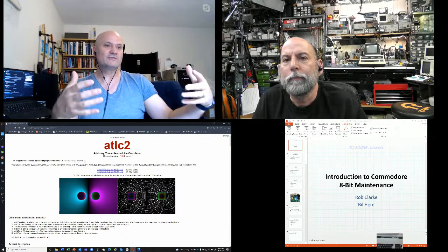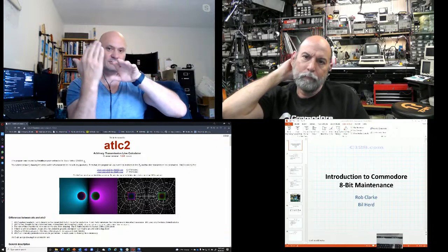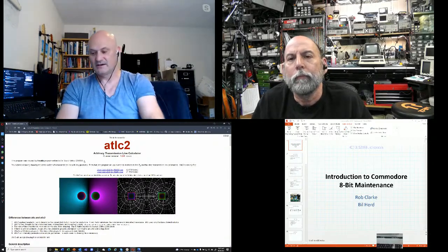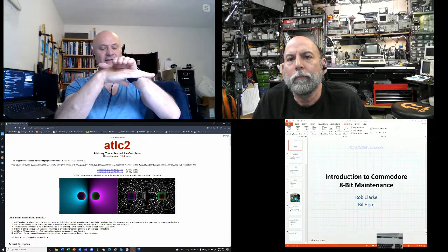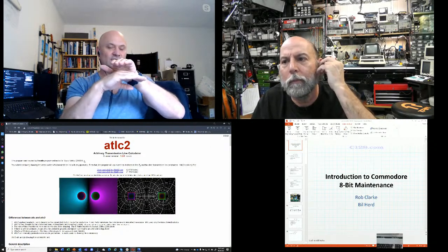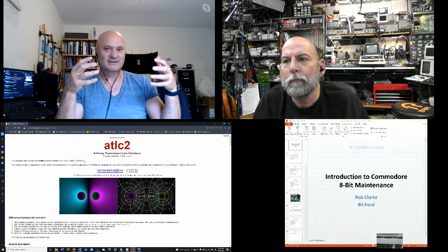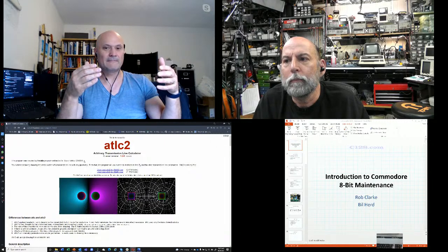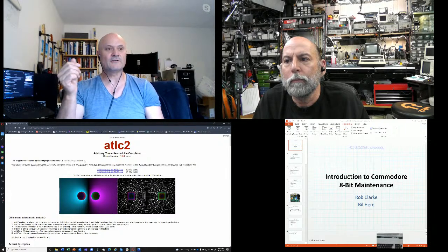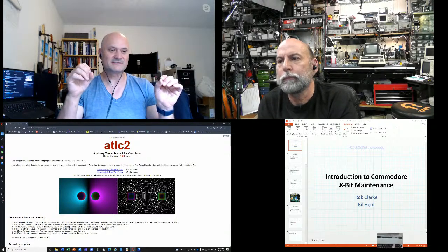And we can do the same thing if you have a theoretical conductor. Just take the cross section of a conductor like a PCB. You have a ground plane and you have a microstrip line, and you look at that conductor cross section, and you divide that whole thing up into a mesh, and the field solver can either model it as resistances at DC, or in the case of ATLC, modeling it as capacitances.